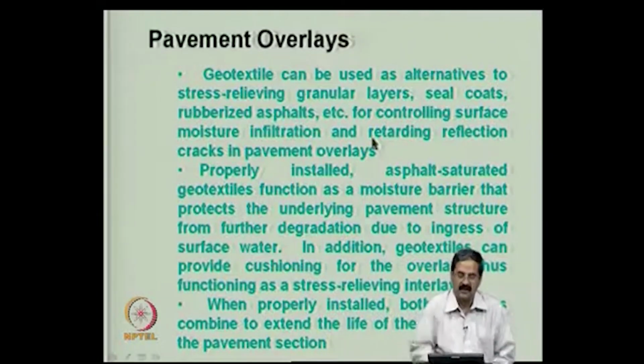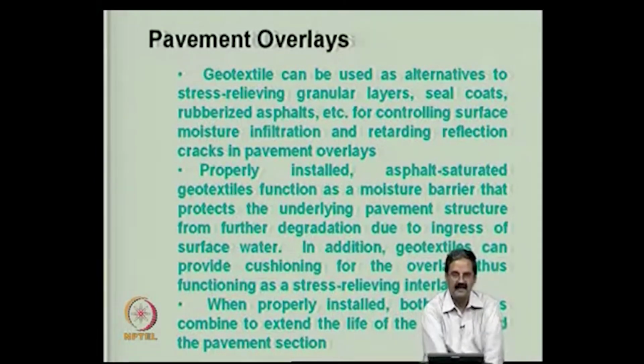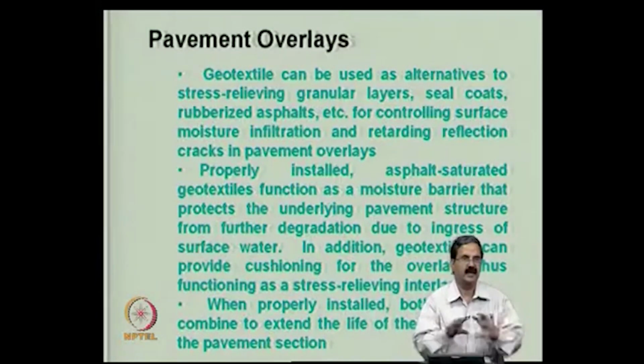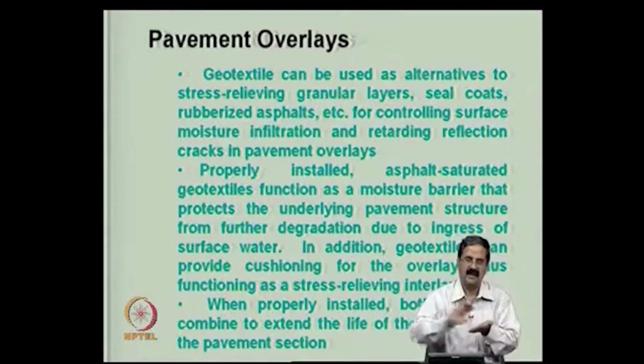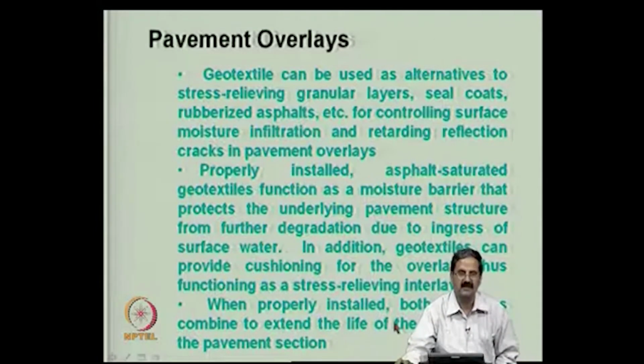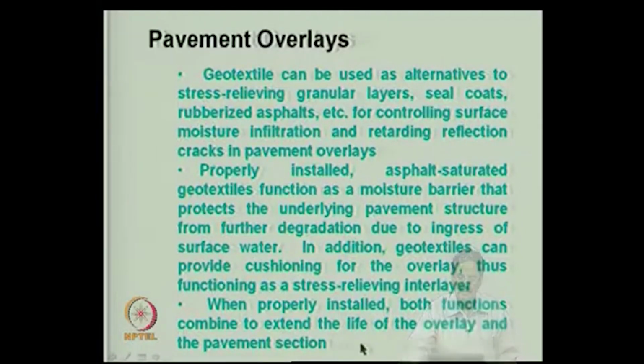So, geotextile acts as a stress relieving layer. Undoubtedly it acts as a stress relieving layer, because it can take some load, and when you install it properly, there is a method of installation, like the way it should be cleaned properly. There are different types of failure, like debonding, which is quite normal, that is delamination, because layers are all constructed in layers and in road work the layers come out. If you are able to use geotextiles, and there are some more products, one can effectively increase the life of the overlay and also the pavement section. That is a very important thing, and they are also cost effective.